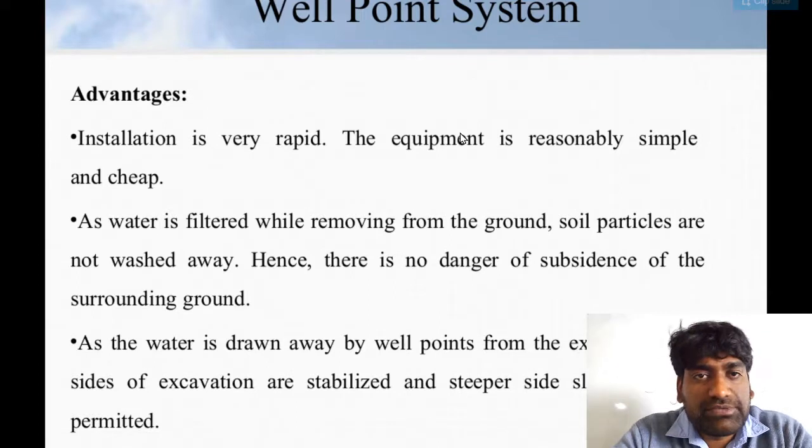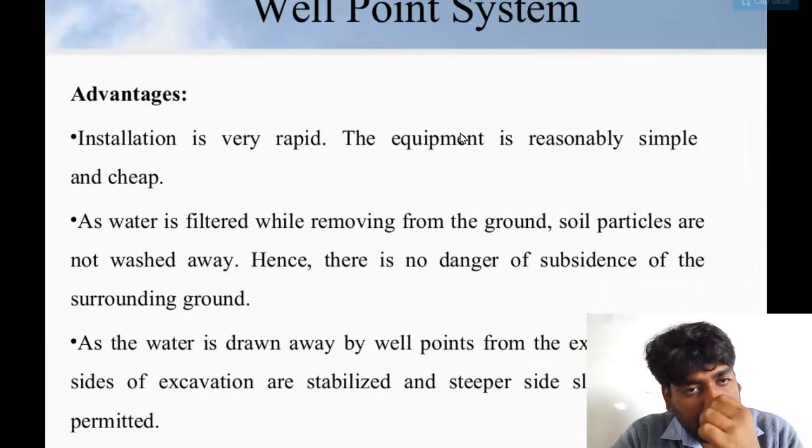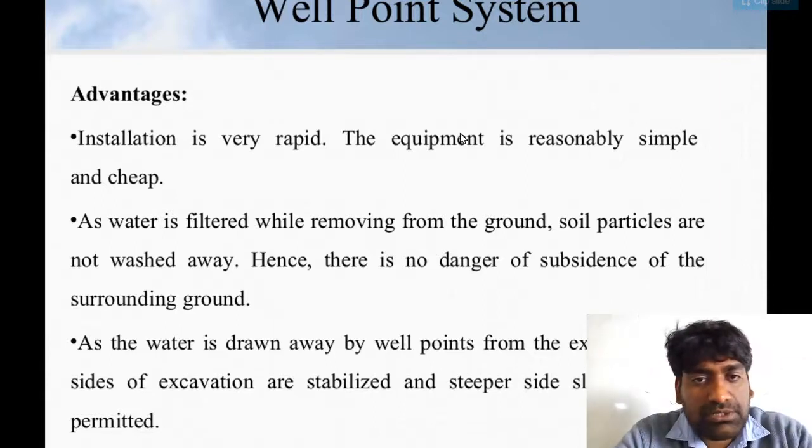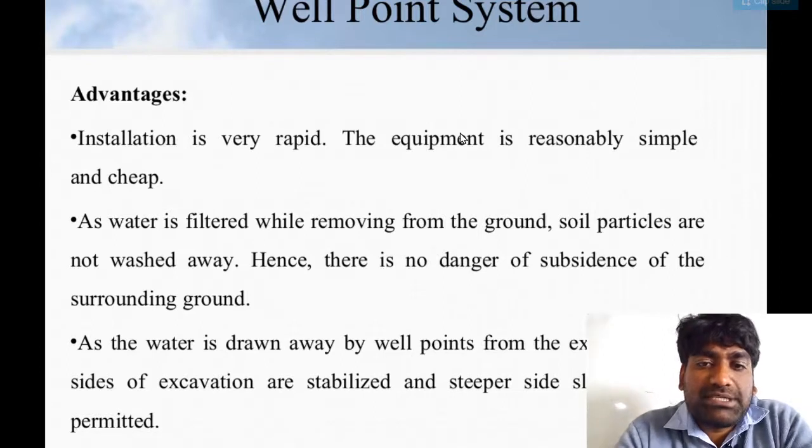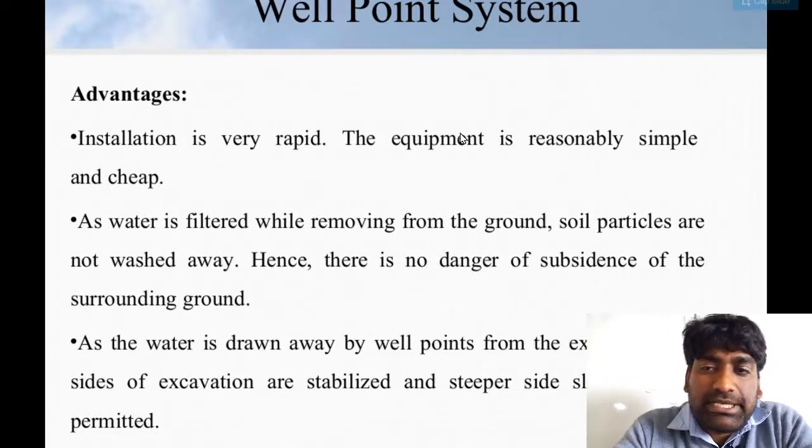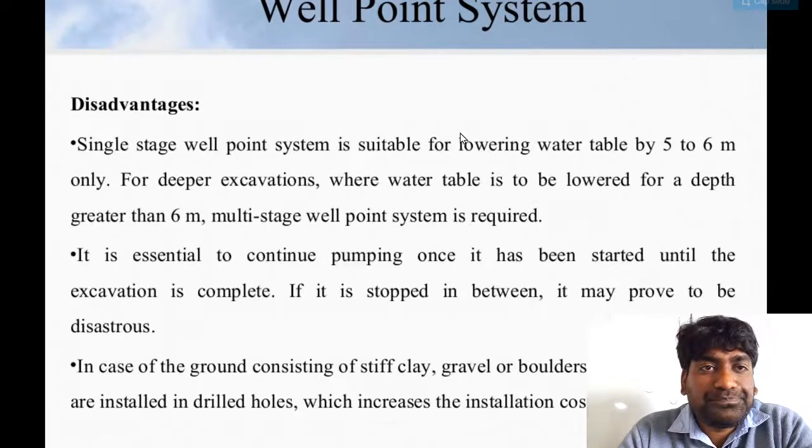Advantages: installation is very rapid, and the equipment is reasonably simple and cheap. As water is filtered while being removed from the ground, soil particles are not washed away, hence there is no danger of subsidence of the surrounding ground. As the water is drawn away by the well point from the excavation, the sides of the excavation are stabilized, so steeper side slopes can be permitted.